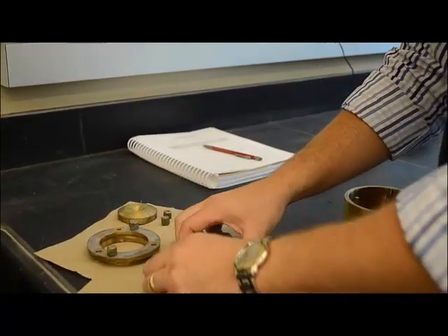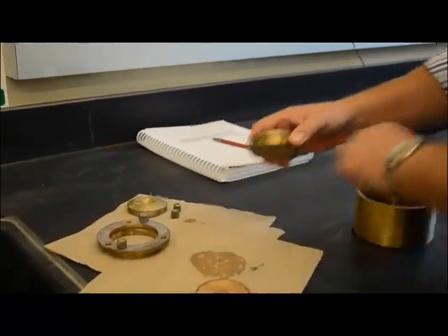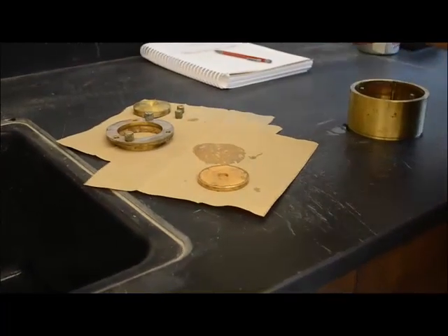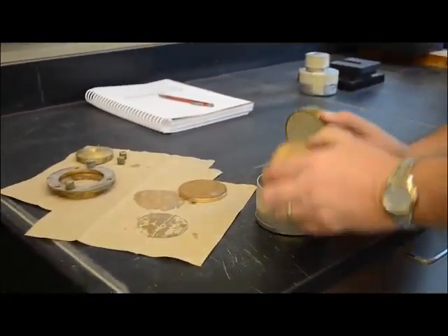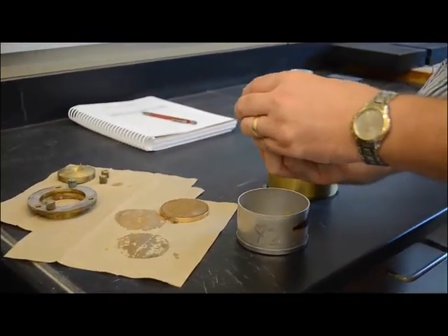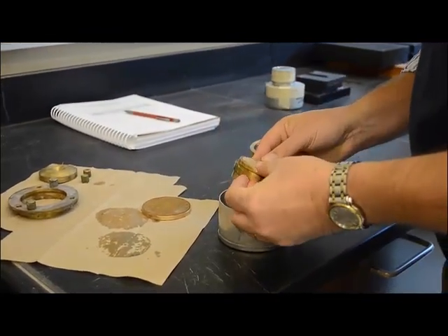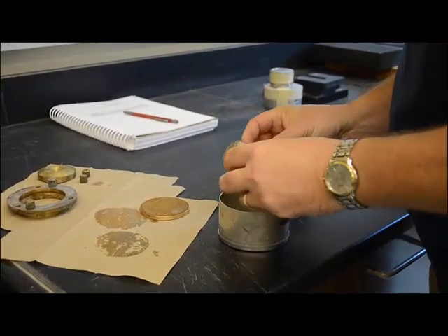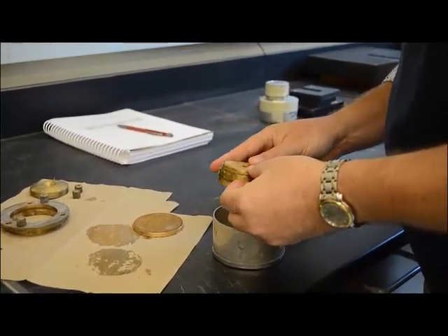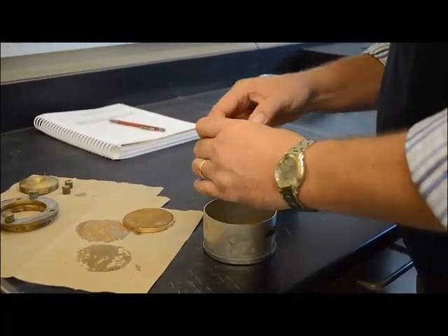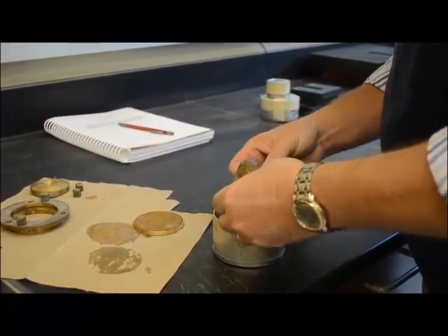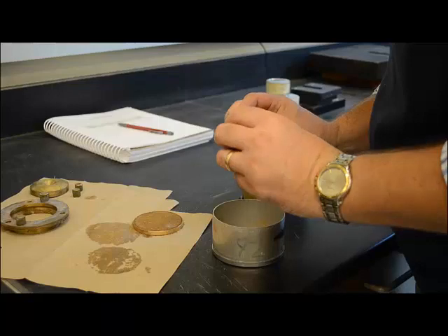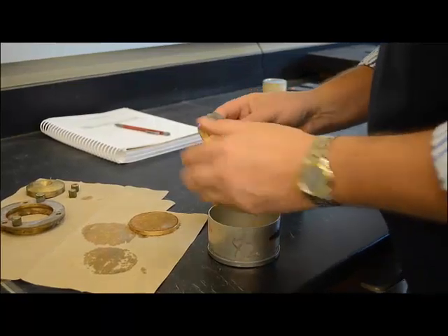I've got my soil sample here. You can see that the sample is much smaller in height, obviously because of the load that was placed on it. And now what I would do is I take that porous stone and I push out that soil sample that has now been saturated over a long period of time. And I push that out of the loading ring so we can get it into a dish. And so we can get the moisture content of the sample afterwards.